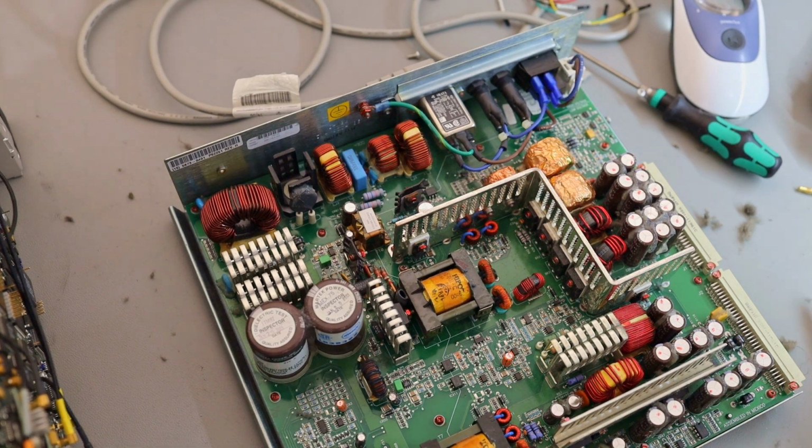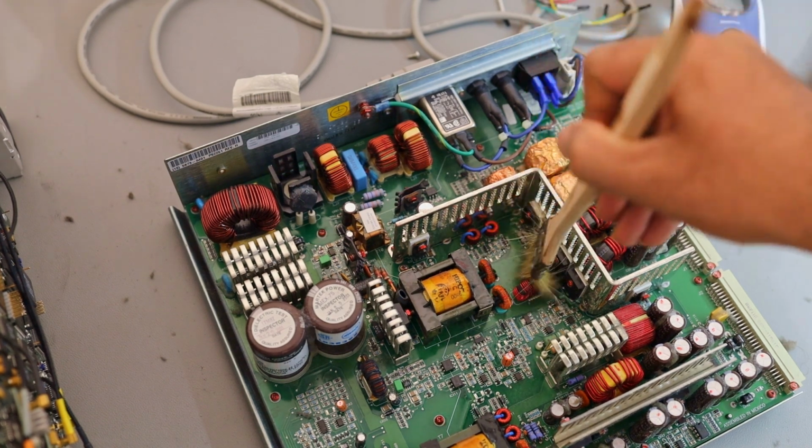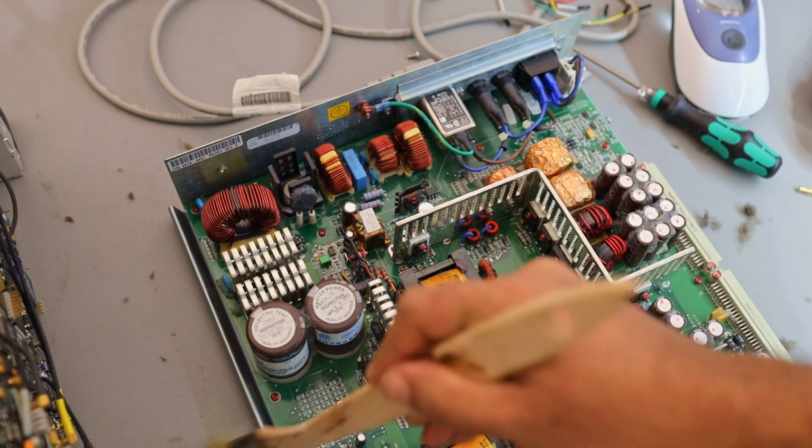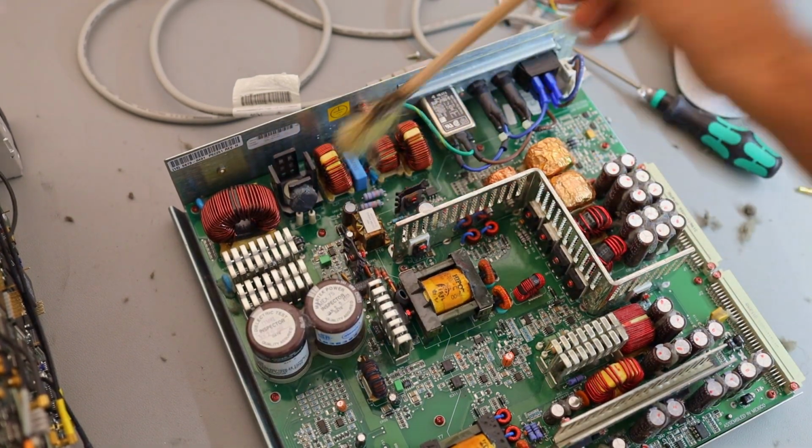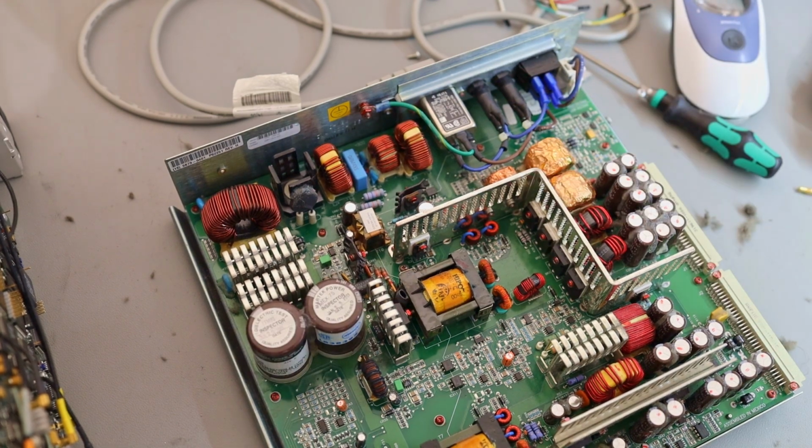So the board is sitting on the ESD mat and also connected to the mains but not turned on. And I'll have lightly brushed it. I'll also brush it a little bit more. Remove everything which is not appropriate. Maybe we can inspect it a little bit if something is burned out or capacitors, any of them are